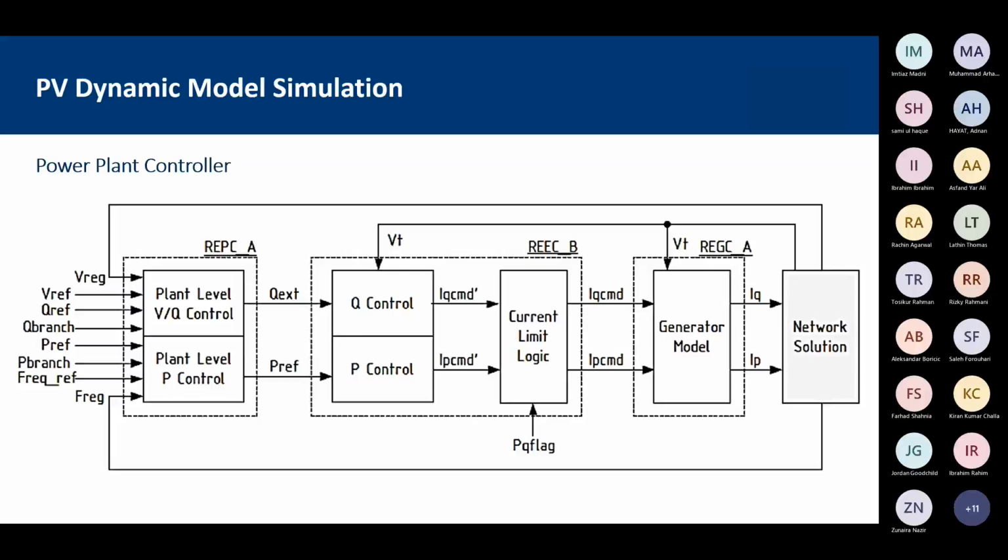Because just like voltage ride-through, it also has to have frequency ride-through, where if frequency changes, for example, to 51 hertz for some time period, it needs to be able to maintain its operation, because if it doesn't, then it can cause even more problems for the grid. And that's what we call the avalanche effect.